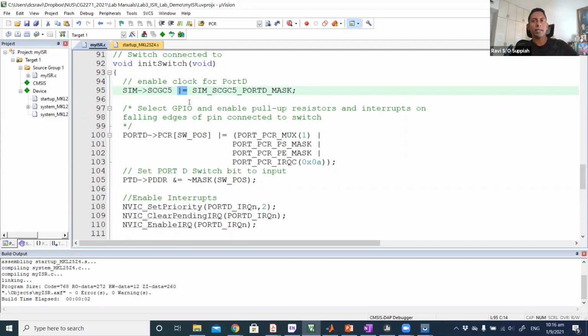The bit masking and the OR and AND, all this stuff is important, because you're going to have a lot more functions and a lot more code as you go along. If any one of those functions does a direct write instead of using bit masking, you're going to override everything that you did earlier, and suddenly everything is not working. So this is very important. By using bit masking, you do not interfere with other settings done in earlier functions. That's the first thing.